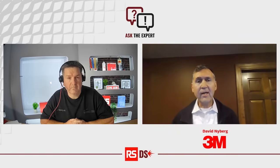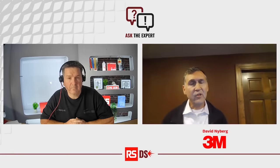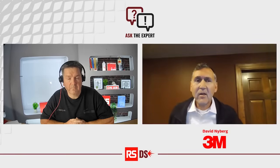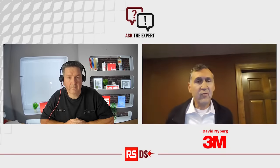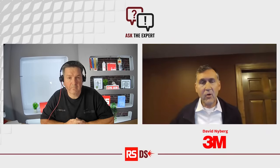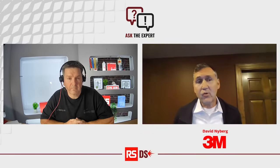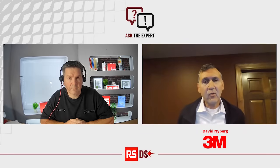CoaXPress, on the other hand, is higher speed, typically longer lengths. A single cable for CXP12 is 12.5 gig, and a lot of camera makers do a version of their cameras where they support a 4X bundle of that, so you can get up to 50 gig on a certain interface with CoaXPress. So CoaXPress is probably one of the most widely used interfaces in the world.